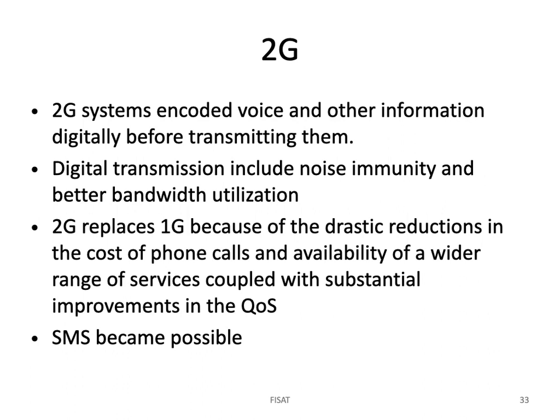During second generation, cellular phones were used for data along with voice. Some of the key features of 2G were data speed of up to 64 kbps, use of digital signals instead of analog, enabled services such as SMS and MMS or multimedia message services, and provided better quality of voice. It used a bandwidth of 30 to 200 kilohertz.